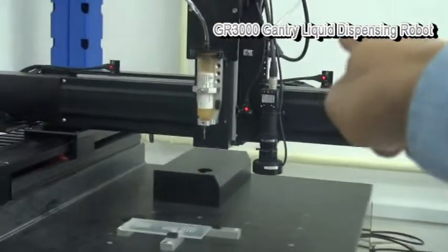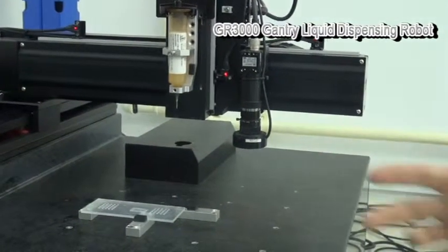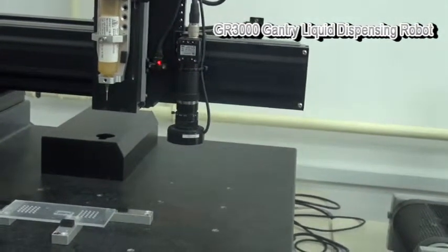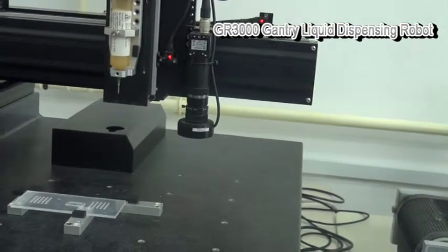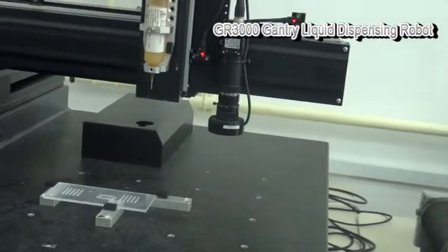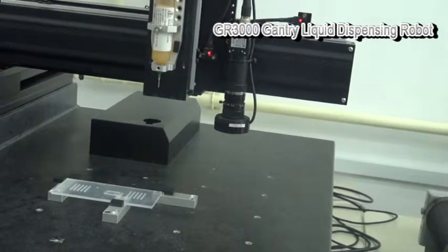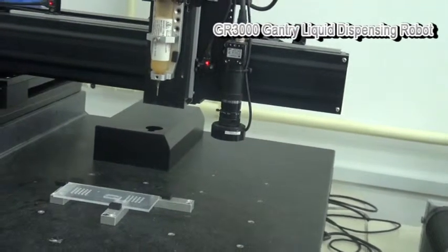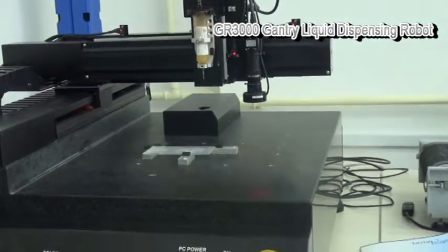Mr. Lea, what's the use of that camera then? This is the fiducial, for fiducial alignment. In other words, every time you put a board on it, the board may not always be in the same position. So this is to recognize the position of the board and compensate for it, such that you always dispense at the location you want on the board. The robot itself does not go back to the same position, but you make sure that it dispenses on the same location on the board. Okay, I understand. Yes. Basically okay.